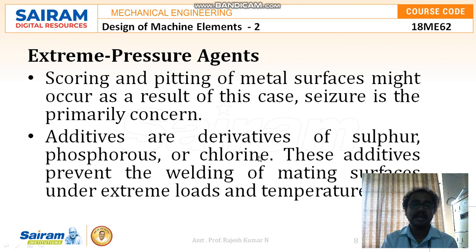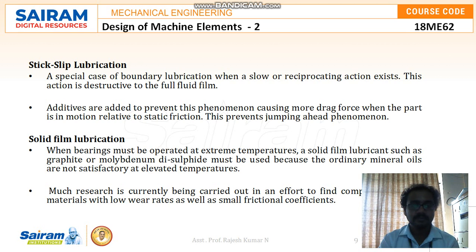The next one is extreme pressure agents, where scoring and pitting of metal surfaces might occur. Seizure is the primary concern, but the additives, which are derivatives of sulfur, phosphorus or chlorine, prevent the welding of mating surfaces under extreme loads and temperatures.